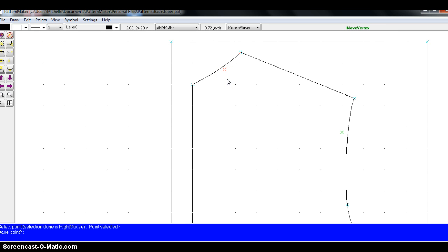Now we need to set our base point, so a single click, and then we can start to pull, and you can see that we're going to reshape the arc. It's usually best to reshape arcs by viewing it by eye, so don't worry about using any snap points in this.